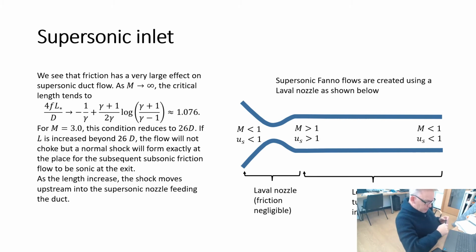And so that's what happens. As we've dealt with in our isentropic analysis for flow through changing cross-section area, where we switch from a supersonic to a subsonic state with the presence of a normal shock in order that the outlet pressure is matched, exactly the same happens here.